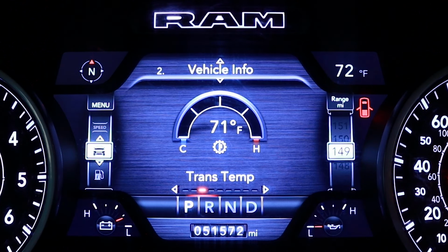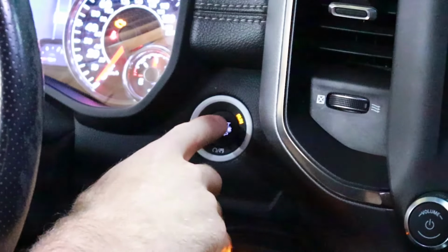If the temperature is above 86 degrees when starting, you will likely run out of time when later performing the remaining transmission fluid filling and leveling procedure steps by exceeding the 122 degree maximum fluid level temperature limit. We suggest all Ram 1500 transmission fluid changes be performed when the ambient temperature is below 90 degrees. All temperatures referenced in this how-to tutorial will refer to Fahrenheit temperature readings.